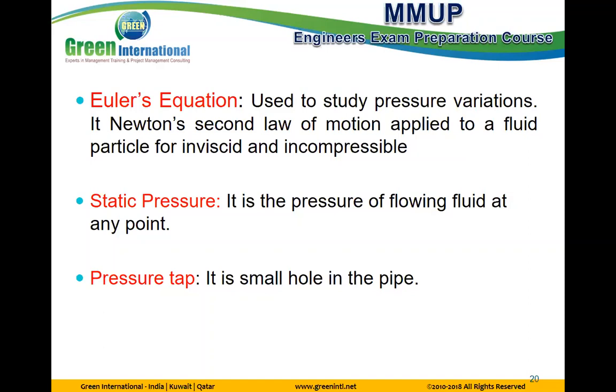Static pressure is the pressure of the flowing fluid at any point. This is the definition of static pressure. Same like the piezometer. You remember the piezometer? Just the pipe above the tube, and the rise is related to the effect of the pressure at the point. A pressure tap is a small hole in the pipe.